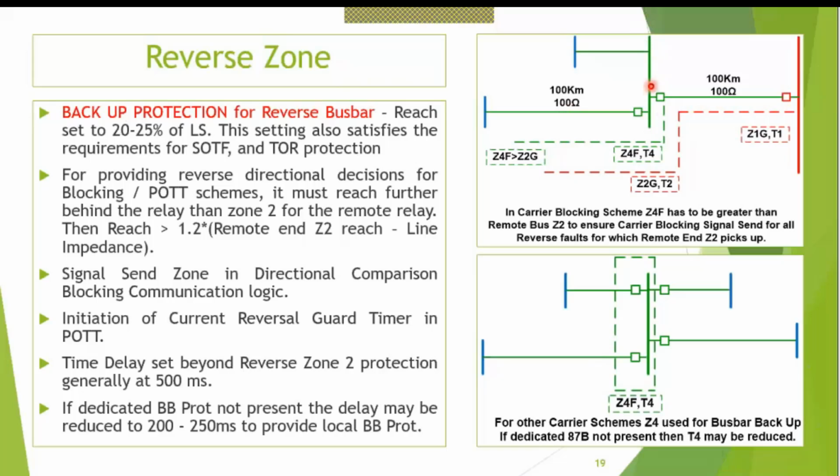Suppose there is no busbar protection on this particular bus, and there is a fault after that, it will be fed from this line. For SOTF also this backup reverse zone is important. So what I need is to cover the local busbar with this reverse zone protection. Normally that is the philosophy.